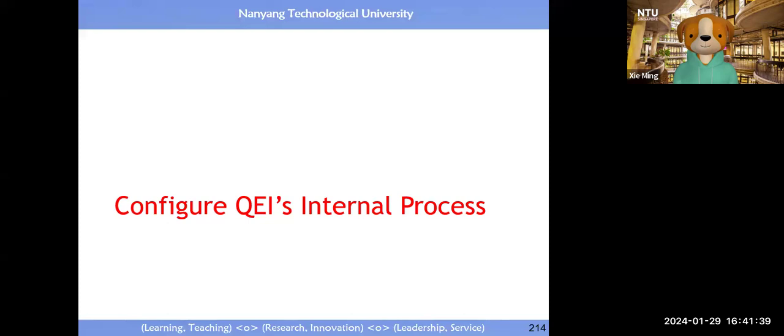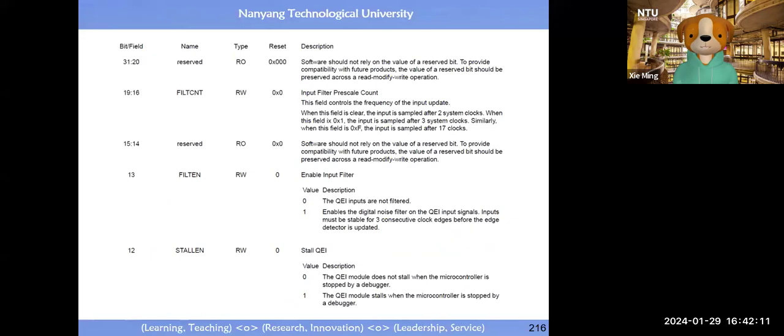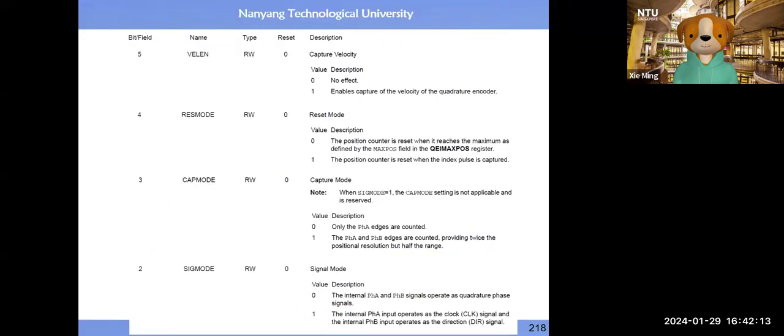Okay. So then the process is to configure all these, whether you want to enable it or not, and enable velocity, but you need to read all the detail. What is a velocity divider? Just now I mentioned it, it is here. You have a velocity pre-divider. If your motor is already high speed, this is how to slow it down to do the counting. All this you can write there, all these values you can set up. The detail you can read, right? So configure this built-in solution.